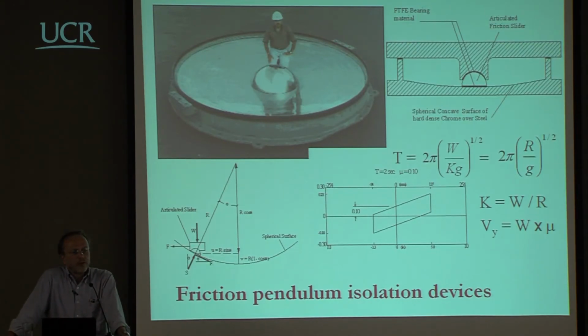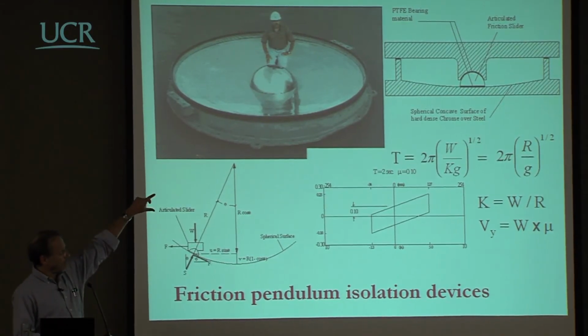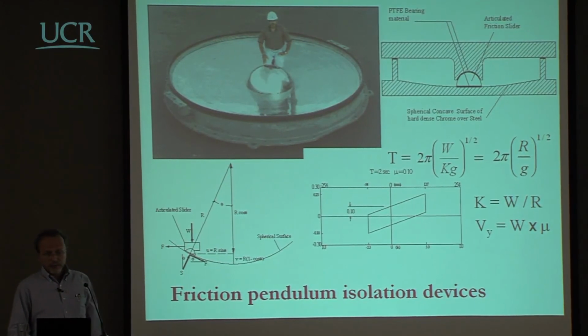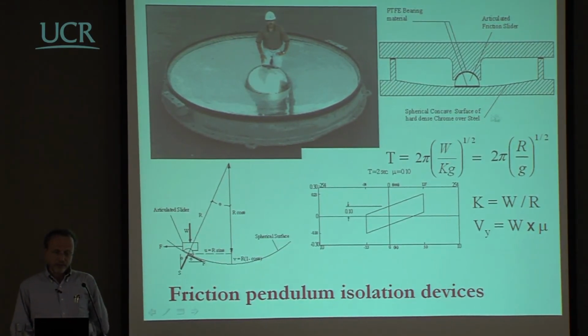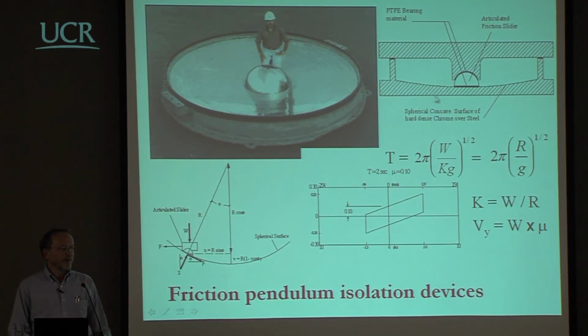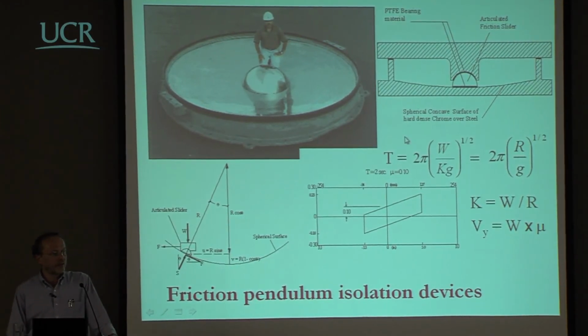We used what are still called friction pendulum systems, that I will discuss in some detail tomorrow, which are devices where you have some curved surface and some other, which is connected either to the pier or to the beam or to the deck, because you could use this in this direction or upside down. Actually, normally they are mounted upside down so that no dirt will form. They will be less sensitive to dust and so on.